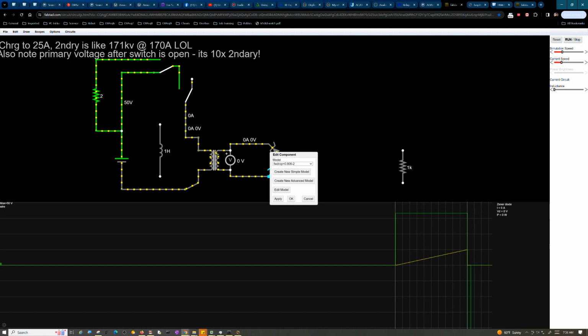So I don't even know if you would want to put 1 amp through the primary since it's DC. But that's how I would do it if I were doing this as a real transformer. I might use like a 10 volt power supply. Preferably one that's not electronic, just to be safe, maybe. It'll probably be fine as long as you're charging up with a resistor. But the point is to get it up to like 1/10 of an amp or something like that.